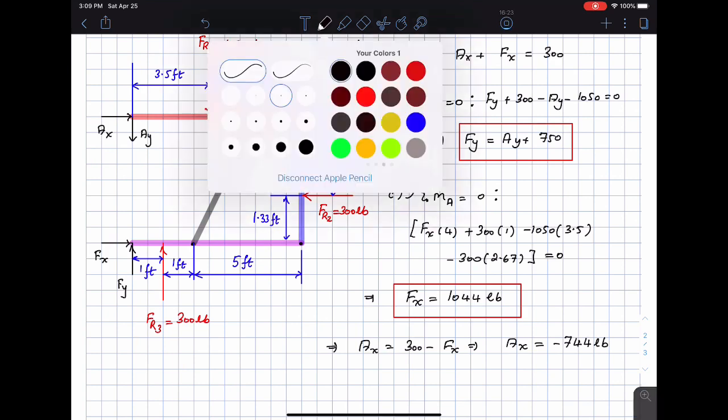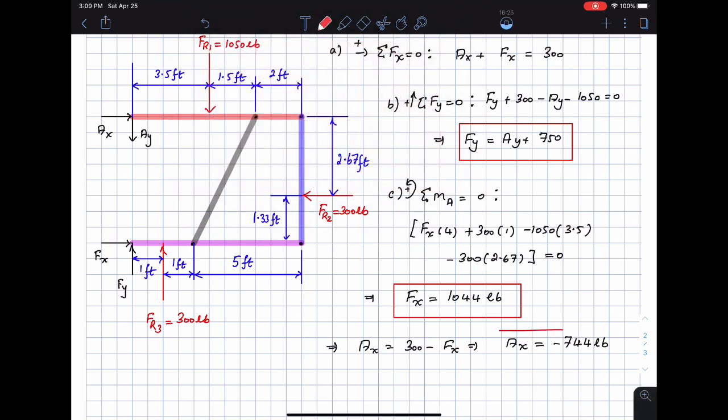Okay, so these are the equations that I have obtained by looking at the free body diagram of the entire frame. Not very useful, but at least somewhat useful. Not a terrible thing. I have at least found out two of the unknowns. I have a relationship between the other two unknowns. Which means that to proceed further with the problem, I have to completely dismantle the frame.